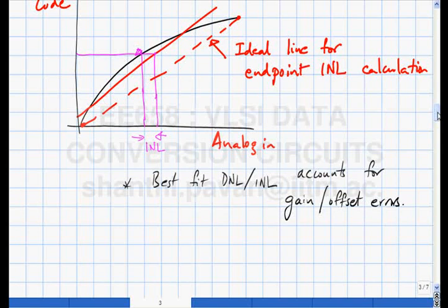But if there is a general slow trend, let's say on your TV screen, if the pink on the left side was not quite the same as the pink on the right side, you won't notice. But if, for example, there is a missing code in the AD converter, which basically means that there is a big jump in the DNL, then one pixel will have such a jump in contrast at that point that the eye will immediately catch it.